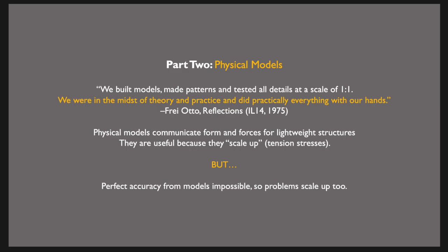is that these physical models that they made were meant to communicate the form and the forces of the lightweight structures. There's really only, again, the model form is found. It's not just found, but these things could also be measured. Super important point. Because these deal with tension stresses, you can actually scale up different models and track how much stress it would be in a full-scale model.